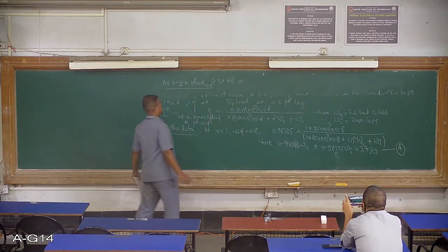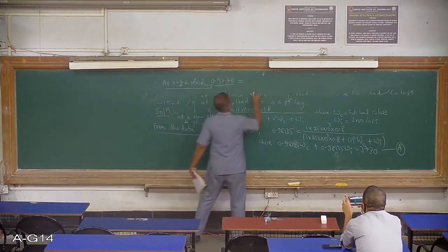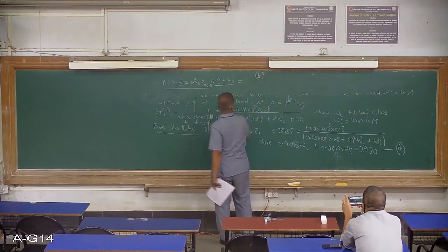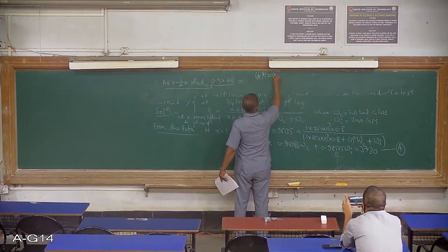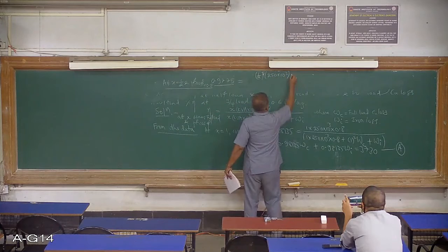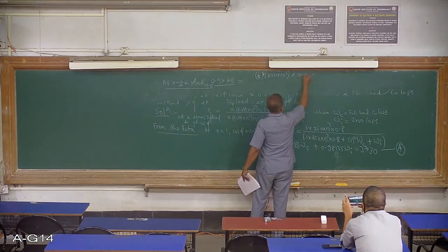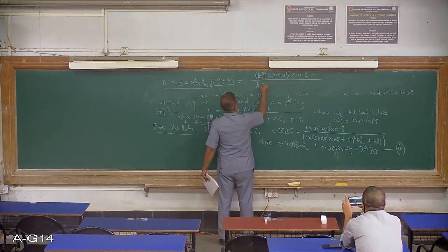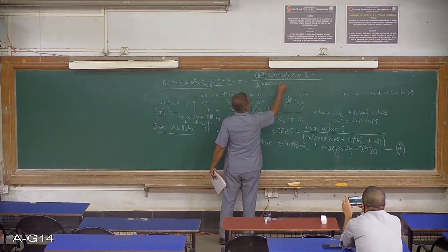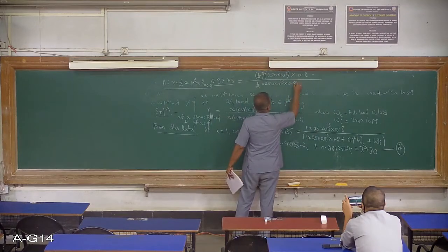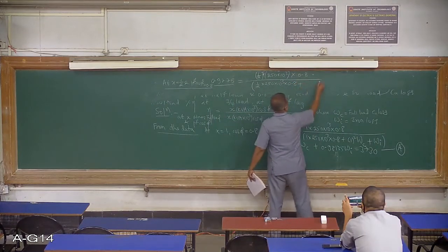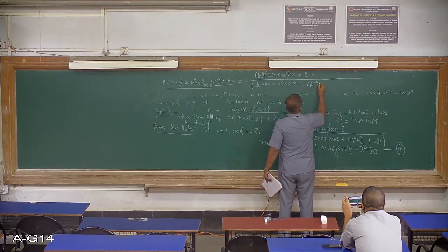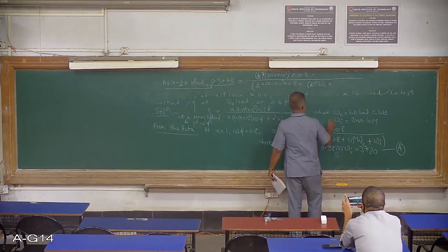That is the second case. Substitute in place of X, half, because it is half load: kVA 250 into 10 raised to 3 into cos phi, that is 0.8, divided by half into 250 into 10 raised to 3 into 0.8 plus X squared, that is half squared, WC the unknown, and WI.